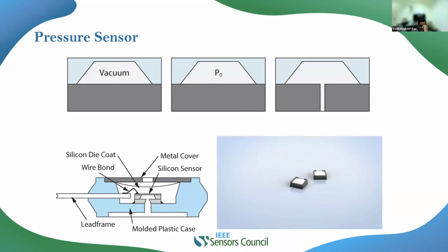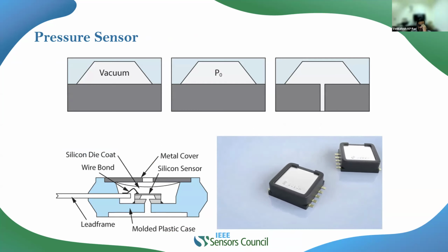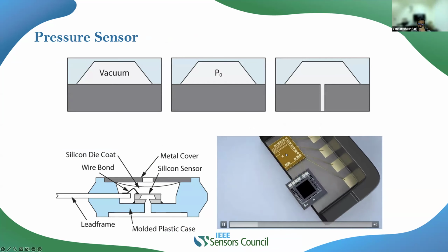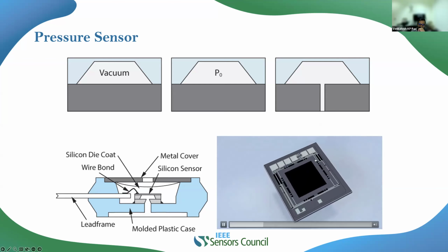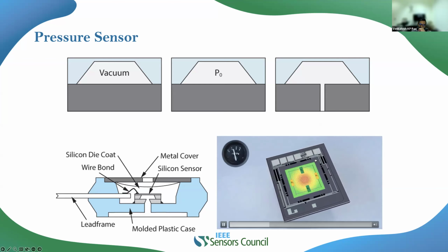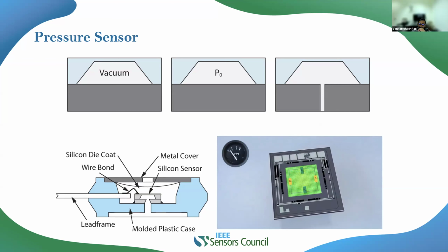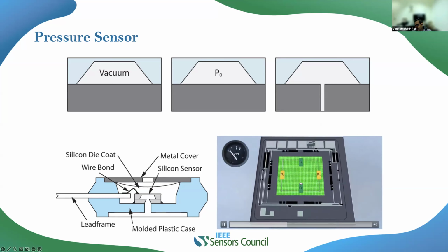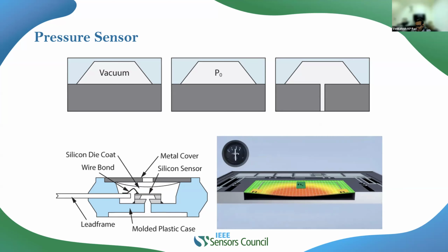The basic working principle of this is that this is a sensor and this is a signal processing circuit. This is a sensor basically. I told you that it's a piezoresistive base. So whenever there is an input pressure, there will be a change in resistance. Then they are connected in a Wheatstone bridge configuration.